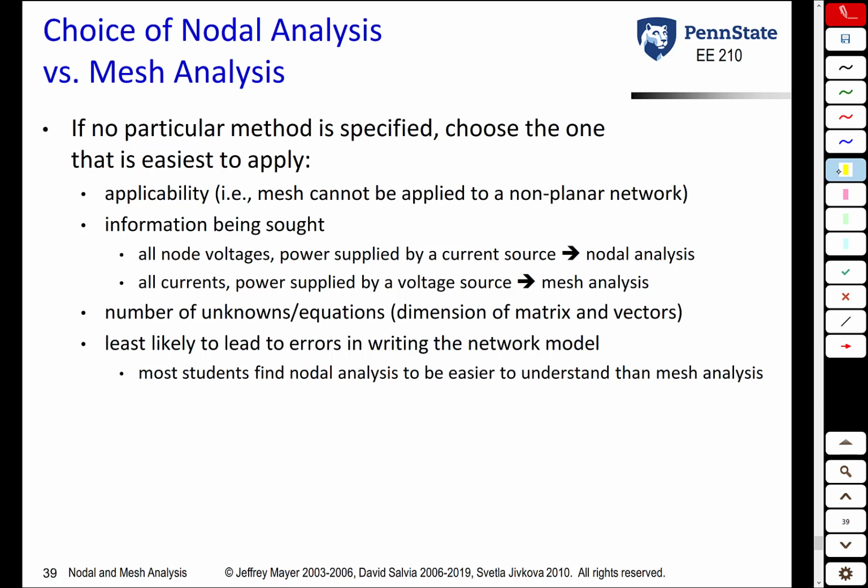However, the mesh analysis algorithm only works for a planar circuit, one that can be drawn 2D. So the first issue is applicability. Nodal analysis is always applicable, mesh analysis not always applicable. In this course, we will not have any non-planar networks, so it's not going to matter, but in the real world, you could certainly have some non-planar networks where mesh analysis just does not work.